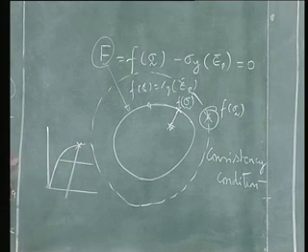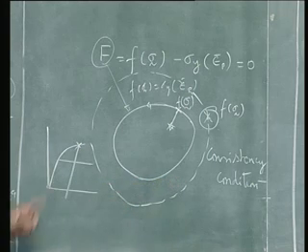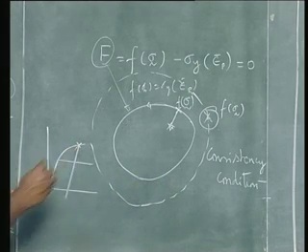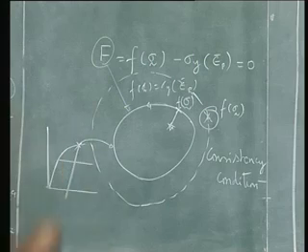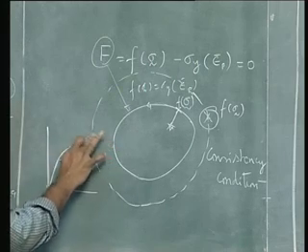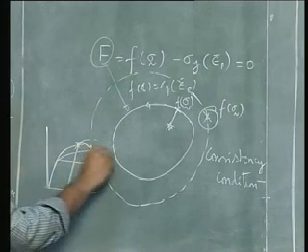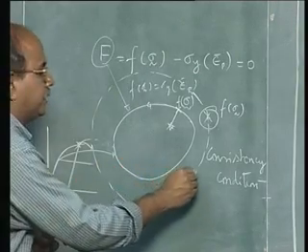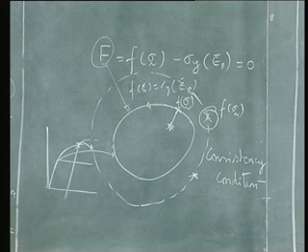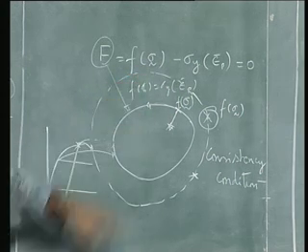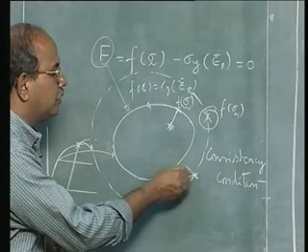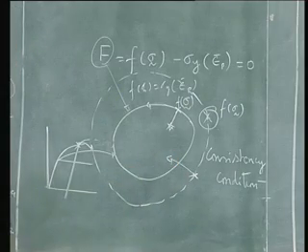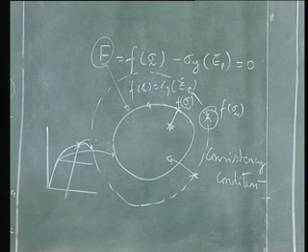The analogous situation in a multi-axial case is that this depicts the yield surface, or rather this point, this yield surface, this depicts that yield surface. So, after I come to say this point on the new yield surface, when I unload or reduce this F, I will go back into the yield surface, but will not take the yield surface along with me, because what has happened has happened.